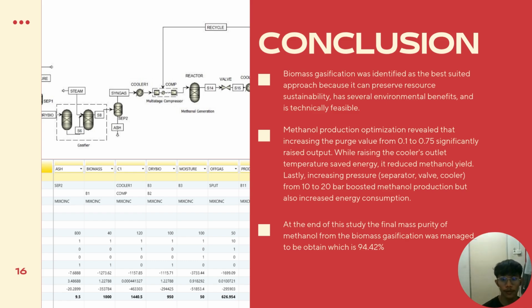Afterwards, the raw syngas went through a comprehensive purification to remove impurities like particulates, tar, acid gases, and inert gases. Then the treated syngas was fed to the methanol reactor, where CO and CO2 are hydrogenated to produce methanol. Unreacted substances like hydrogen, carbon monoxide, and carbon dioxide are recycled back to maintain the efficiency and reduce waste at